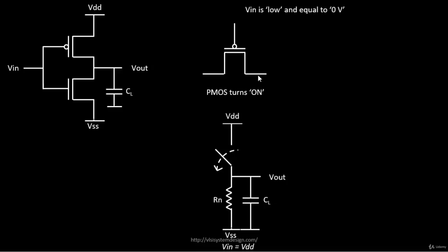We also know that to represent an on transistor, we use a resistor. Whenever there is a direct flow of current from one point to another, the wires are not ideal, and I'll be coming to wires in a bit. The wires are not ideal. They will have some finite resistance because they are physical wires which have a width, depth, length, everything. So we will represent that with RP, the resistance of the PMOS transistor. Rn was used to denote the resistance of NMOS. RP denotes the resistance of PMOS, and very soon we'll be proving that this resistance is a non-linear function of your drain current.